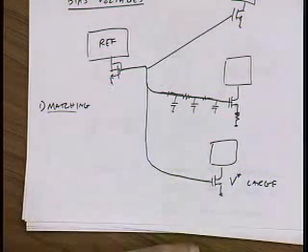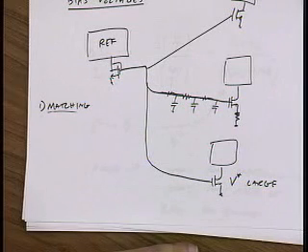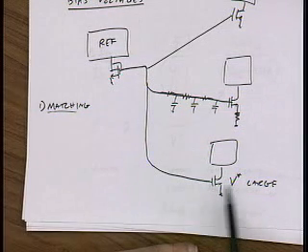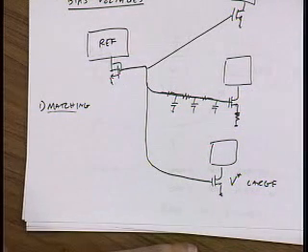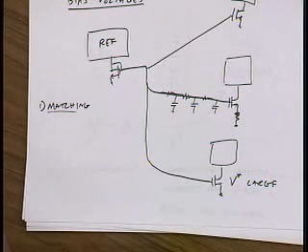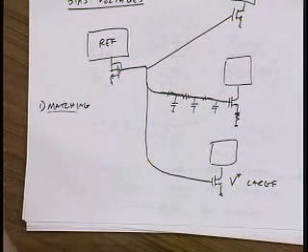How do I solve the problem with swing, right? Anybody have a suggestion? Let's say I want to use this current source as a load for a PMOS amplifier, right? Because it has a large V star, it's great, it has low noise and good matching, but it's going to have a really poor swing.